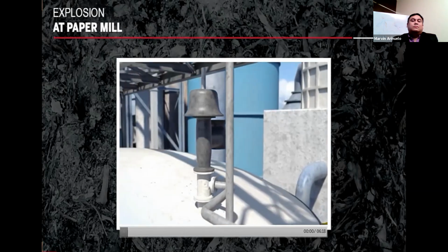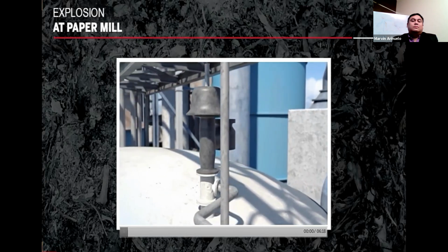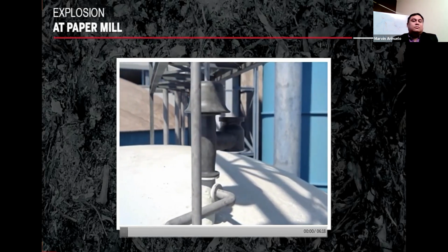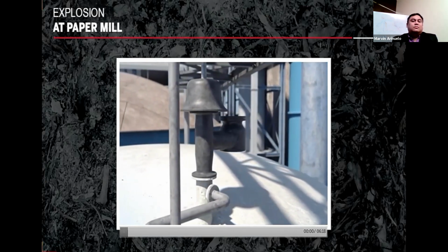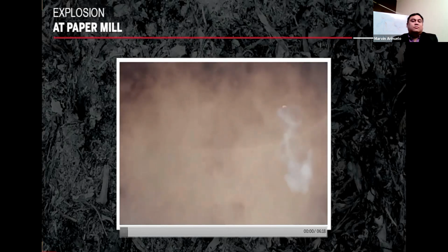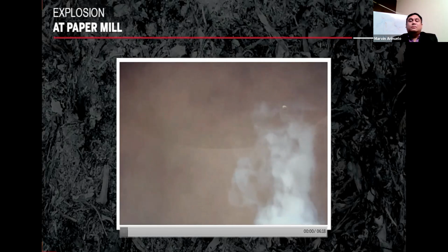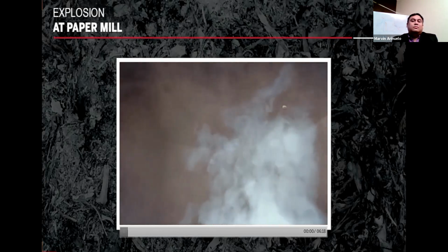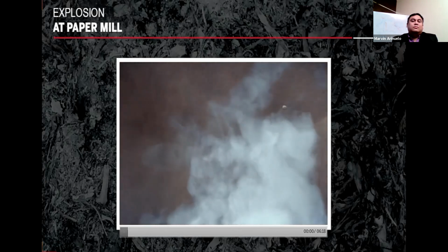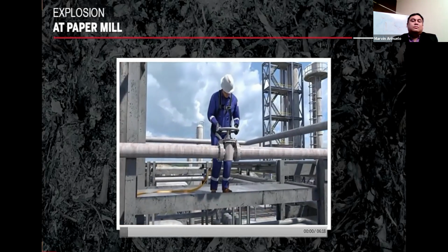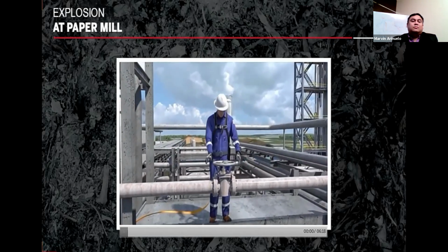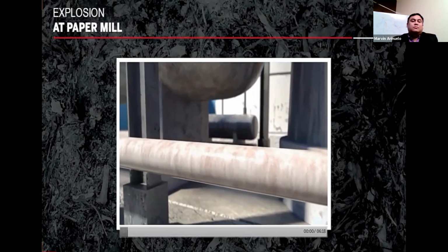This most likely triggered a relief valve on the tank's roof to add more air to avoid damaging the tank from the vacuum created by low pressure. The vacuum relief valve was likely one of the few potential sources that allowed enough air into the tank to create an explosive atmosphere. In preparation for the hot work, the water piping was isolated from the foul condensate tank and the rest of the process by closed valves, and the piping was separated physically from the tank.